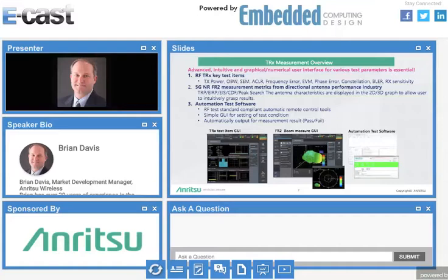So when you start having to test all this stuff, you really need some kind of interface that can show all of these key test items. And these are shared across all of those different standards and technologies that I already mentioned. You've always got to test transmit power, bandwidth, spectrum emission, adjacent channel, frequency error, EVM. You always want to look at your constellation plots and then see how your sensitivity performs. Those are really key aspects, and you want to be able to test those consistently, reliably, and very quickly.